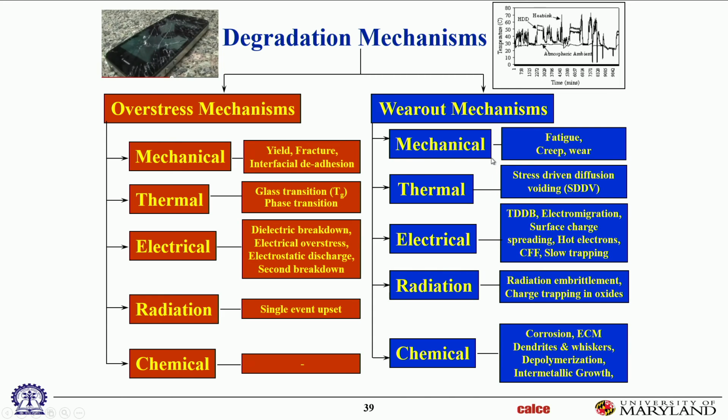But the reality is that multiple stresses can together jointly trigger a given failure mechanism, and vice versa. Mechanical stress can cause multiple failure mechanisms. Electrical stresses can cause multiple failure mechanisms, and so on. Same thing, by the way, with electromigration. It's not just current density, it's even temperature. So there should be a dotted line from temperature to electromigration. I've eliminated all the dotted lines for simplicity. Okay, so that's the second subtlety here.